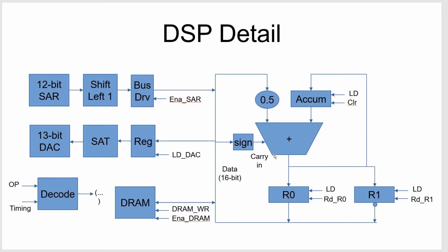And so this has what we call 3 bits of guard band. A guard band means that when we do these operations where we're doing the calculations through here, we can overflow or underflow by a factor of 8 from the original input data. We also have some saturation logic, you see down here it says saturation, so we can calculate if we're going to overflow the accumulator.